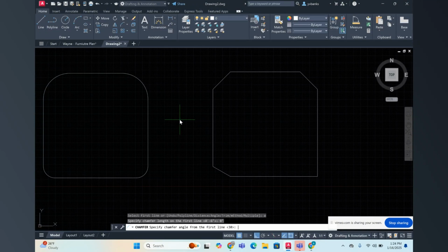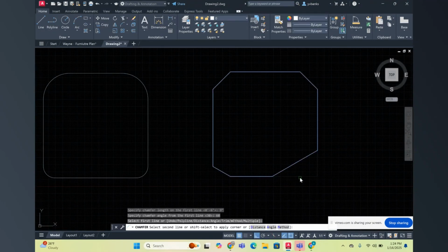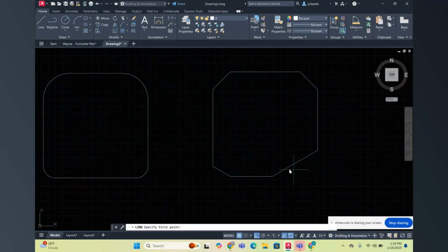And now we want to specify the angle. Let's say we want a 9-inch line drawn at a 60-degree angle. So type in 60 and press enter. Specify the first line and then the second. Much bigger. I'm going to draft myself a little guideline here and then use my measure geom and select angle to verify. So from here to here should be 60 degrees.